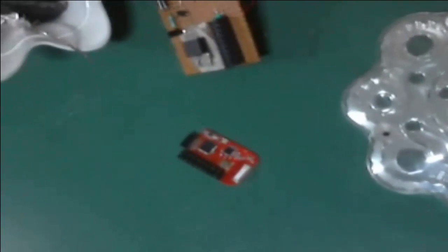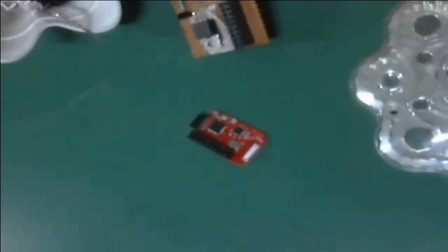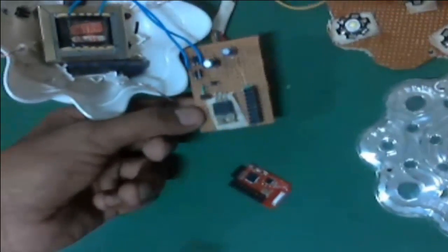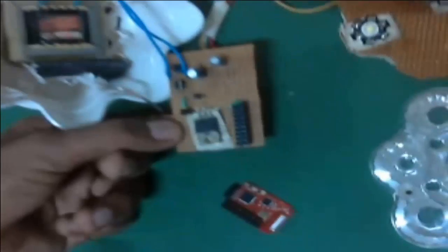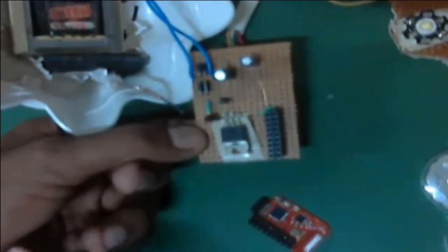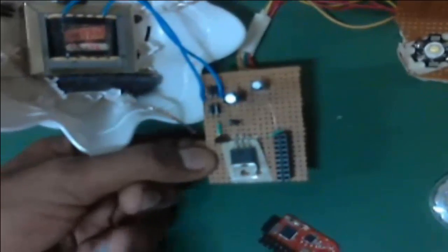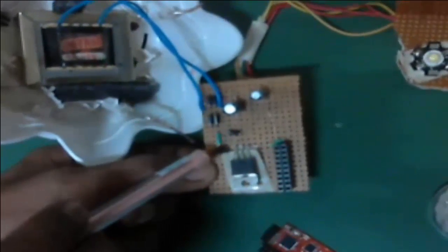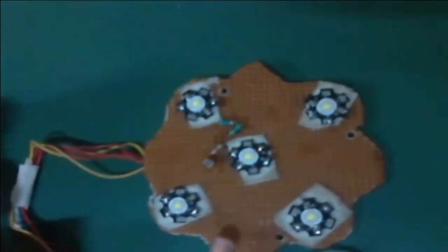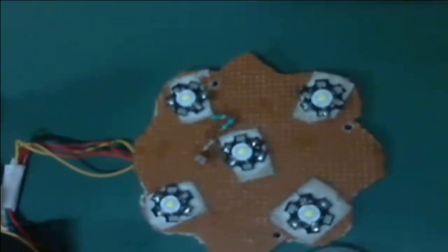This board receives the desired light intensity from the CCU and maintains it in the room using a PID loop, and the PID loop is implemented in this board. Here we have a MOSFET to control the LED panel. The MOSFET cannot be turned on directly using 3.3 volts, so we have a BC547 transistor to control the MOSFET. And here we have the LED panel and an LDR to measure the ambient light intensity.